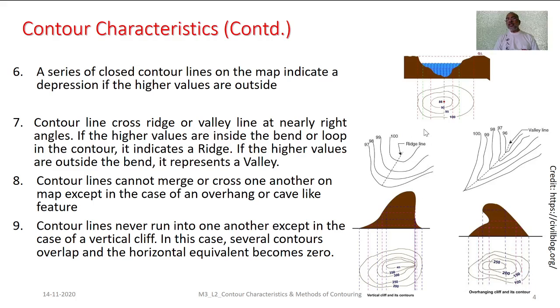Whereas the case here is just the reverse. That is, the contour placed at the innermost has a lower value, whereas the contour placed at the outer end has a higher value. Here, this dotted line will give the valley line. Usually, this valley line can also be correlated with a probable stream existing in that region. Here also, one can make it out easily.